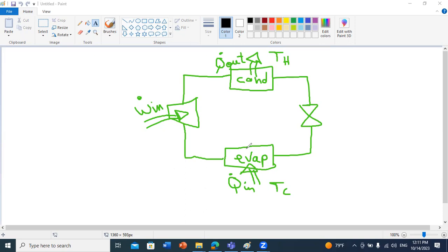Plus, here of course we will not put a turbine for the expansion, because in general we put the turbine in order to produce work. Here we don't want this. We want to have minimal loss of energy. In the theoretical case, we can consider that in our expansion valve we have no loss of heat and work. So the expansion valve will allow expansion at constant enthalpy.